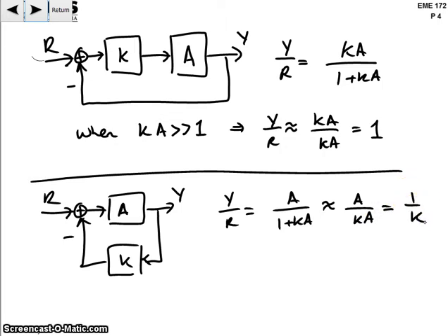Okay, so it's clearly not 1. And the bigger we make k, the smaller we'll make y. So this is still a reasonable controller, but we have to do something to scale the input signal. This is a little bit undesirable, and this is one of the reasons why we often use this cascade compensation approach.